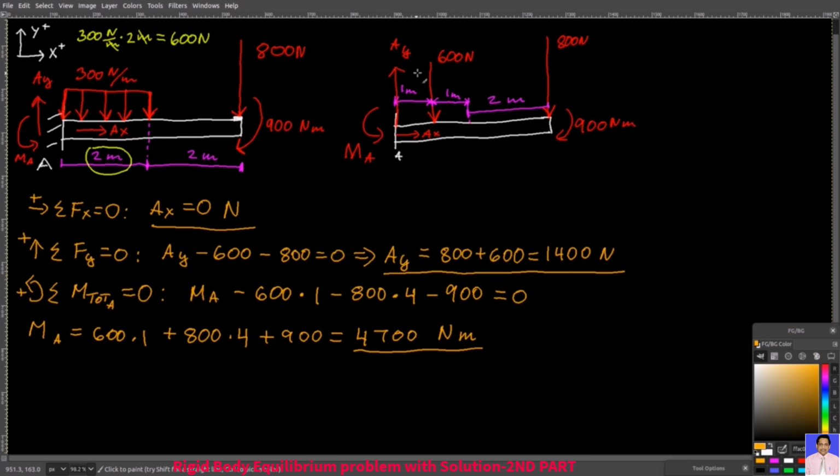But now, it might happen that this support at point A is strong enough to cope with the reaction force AY, but not strong enough to cope with the reaction moment MA. It's like, imagine that you're holding a bag. That bag has a mass, so it also has force of gravity Fg, which points down. In one case, you're holding it closer to your body, in another case, further from the body. In both cases, you have the same reaction force, Ry, that counters Fg.